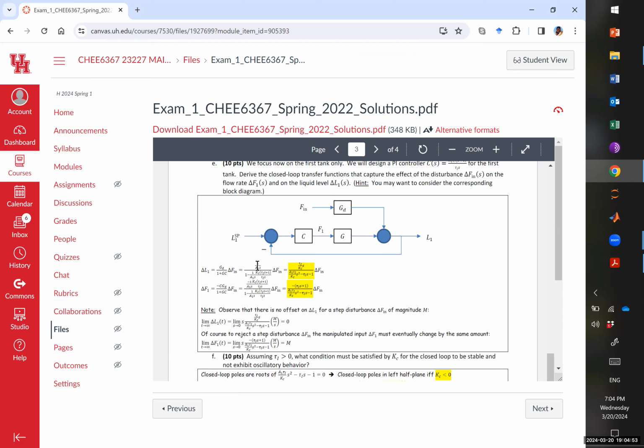So is an integrating process stable or unstable? Strictly speaking, it's unstable in the sense it doesn't go back. If you throw in an input, the input will be integrated, so the output is not going to come back to 0, right? Now, if the input goes to 0, the output is not going to blow up. So it's on the verge between stability and instability. It's critically stable.